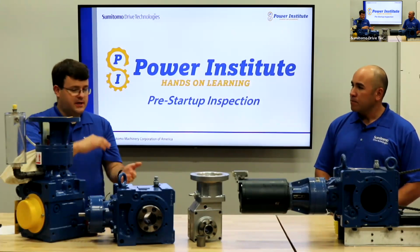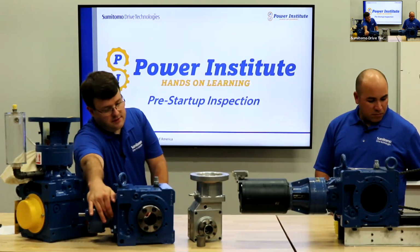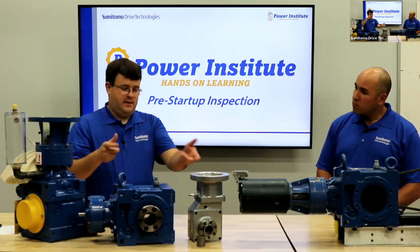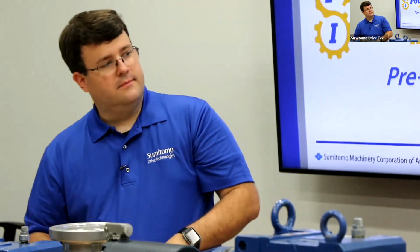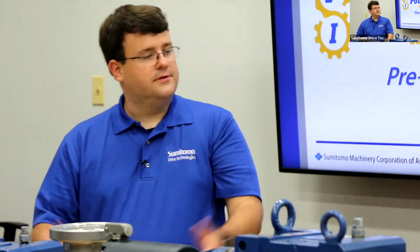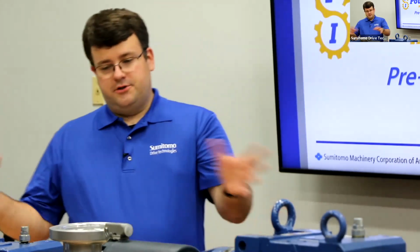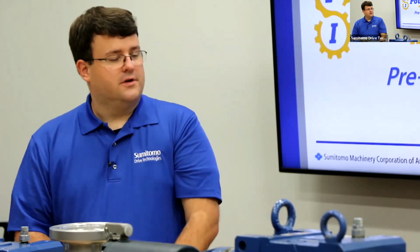Because if you do change, so this one was a grease unit, normally there would be a sight glass right here. If you were to flip it and mount it a different way, the sight glass might not be visible. So you want to keep that in mind to make sure for the long term you can still see where the oil level is and do oil changes and things like that. But as long as you take all those three items into account, you can switch them with the correct direction.